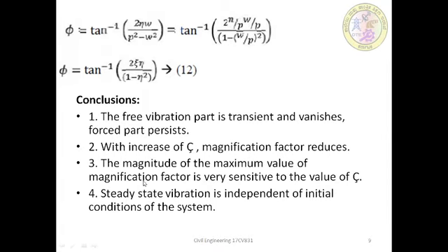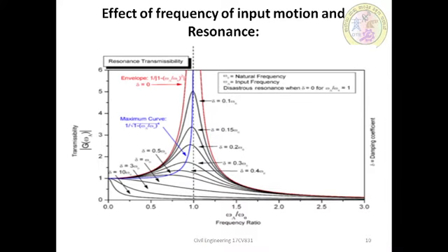So what is resonance? Resonance is a phenomenon of increase in the amplitude that occurs when the frequency of a periodically applied force is equal or very close to the natural frequency of the system on which it acts. When an oscillating force is applied at a resonant frequency of a dynamical system, the system will oscillate at a higher amplitude than when the same force is applied at other, non-resonant frequencies.